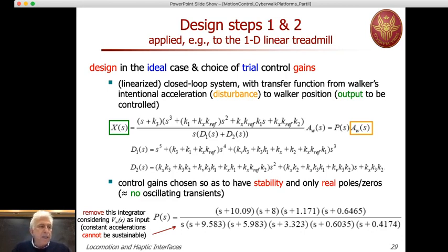We would like this disturbance to have the least effect on the position so that the position can go back to zero or to the reference value that we have chosen, since we are linearizing the closed loop system around zero. So this is our target, bringing it back to zero. Okay, so this just clarifies why this pole in zero can be removed from the picture.